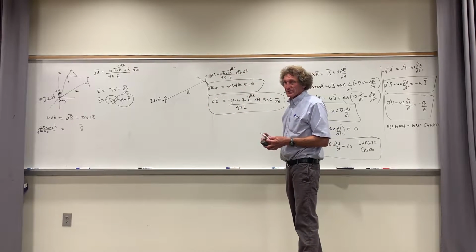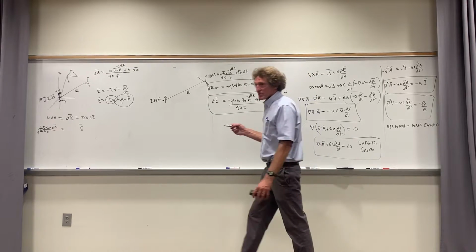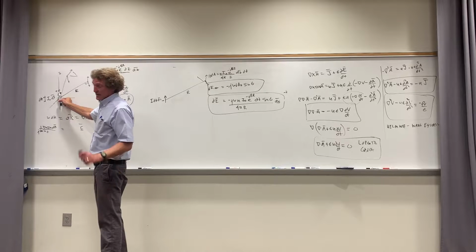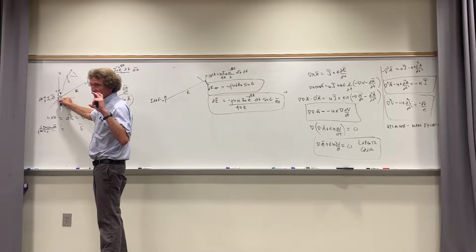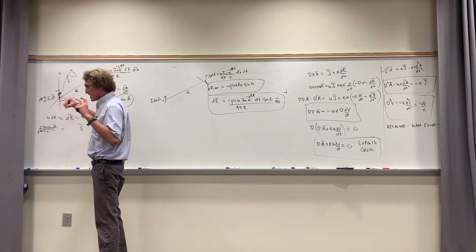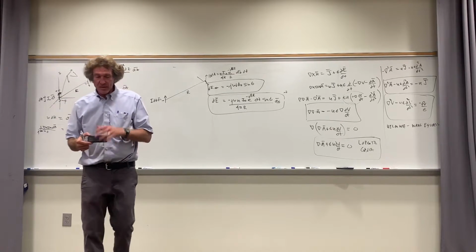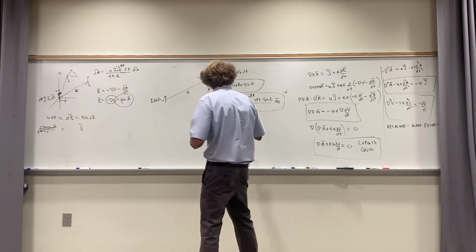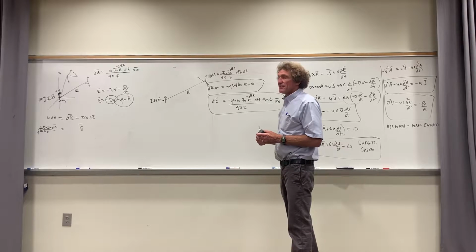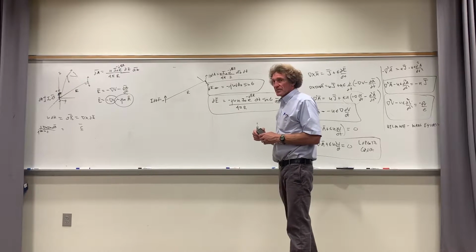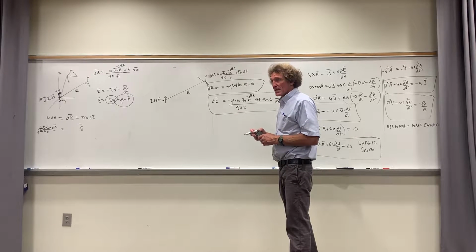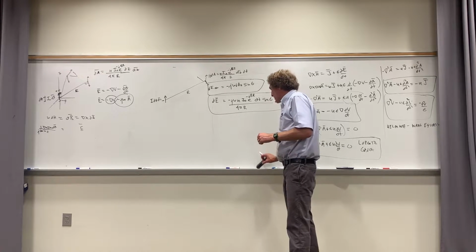All right, so here's the upshot of the whole thing. If you have a small piece of current on the z-axis that has a length dz and a magnitude of I naught, and it's really a time harmonic current, which means it's sinusoidally or cosinusoidally varying, then this is in fact the value of the E field you get. And it's in the a theta direction. I'm going to mention one thing about this. This is the propagating electromagnetic field. It's the field that's going to be launched from an antenna.